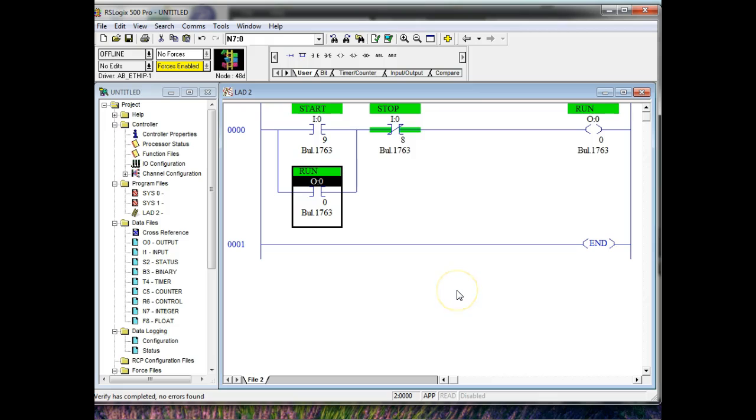Okay? Everybody okay? Now, for some reason, Allen Bradley actually puts the model number down here of the actual PLC or the input module. So if you're on one of the 504s, it'll actually put the model number of the input ports. I think I had it up the other day, right? And while they do that, it really doesn't mean anything. So we're concerned with this and this and this. Everybody okay? And then I would come up here and do what? Now I go and download it.